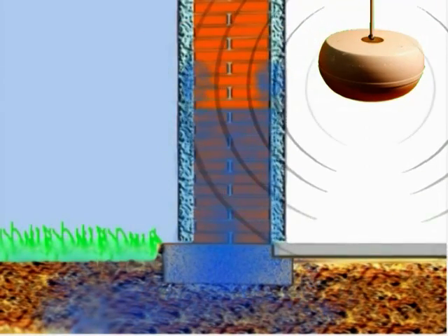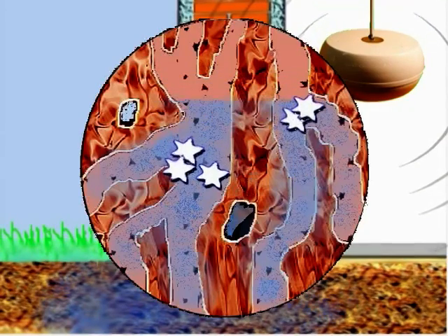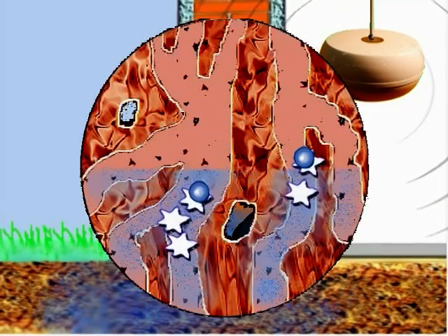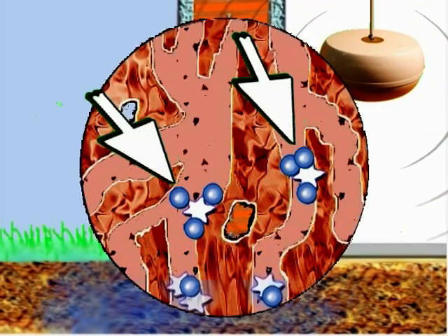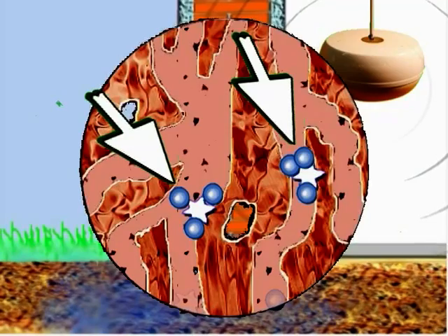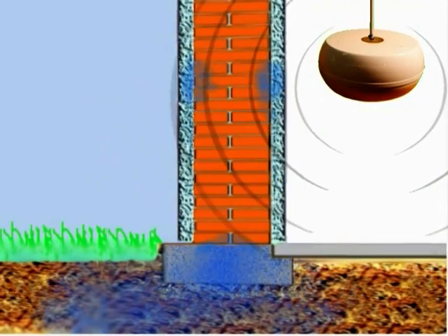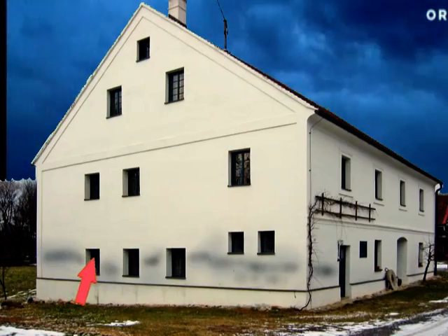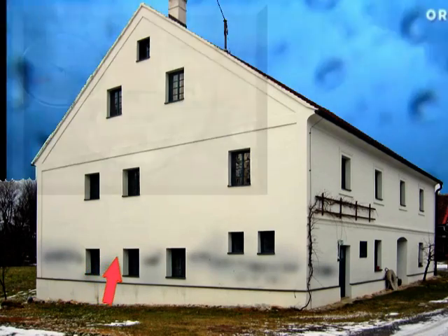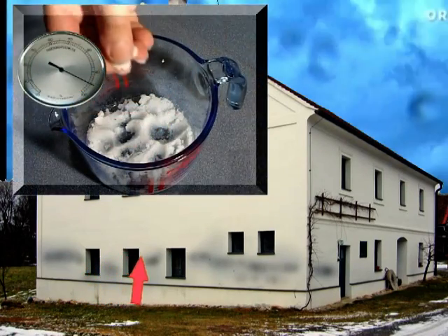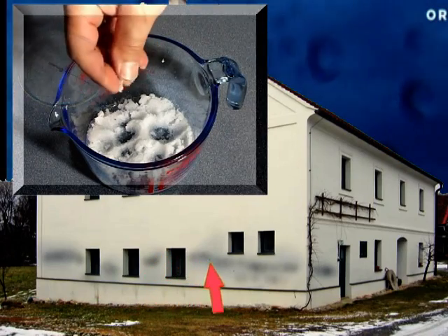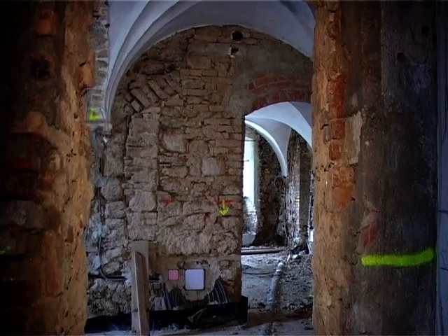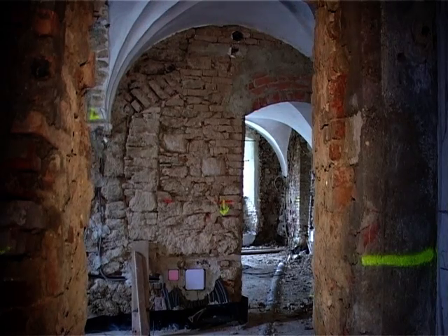However, the large part of the masonry moisture moves back into the ground through the capillary system in the wall, which is the actual phase of dehumidification. What remains is the chemically bound residual moisture in masonry. The external climate might play a major role when walls contain a lot of salt. This is why we occasionally encounter moisture variations due to climatic factors, although the wall will have achieved its level of residual moisture.